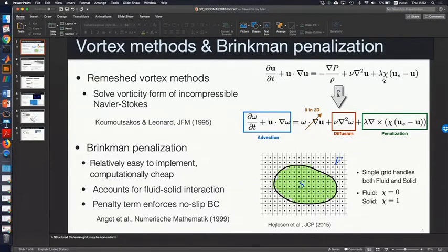Okay. So yeah, this is a very, very simple and very elegant way of imposing the boundary conditions for irregular solids. You can even do the same with walls. Wherever you have a flat wall, you put those grid points as u solid equals 0. That's your boundary condition. And then again, solve the whole thing as your fluid. Okay, any other questions?